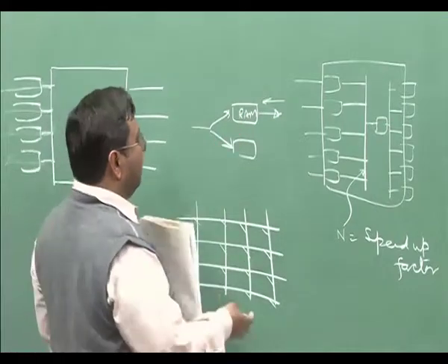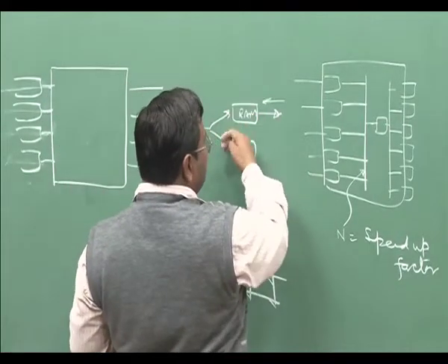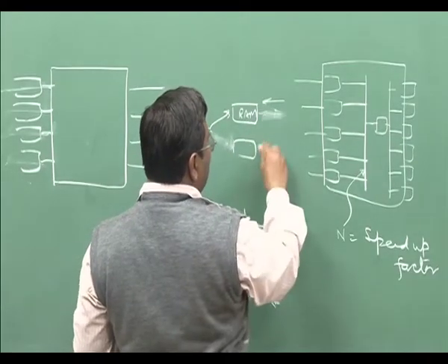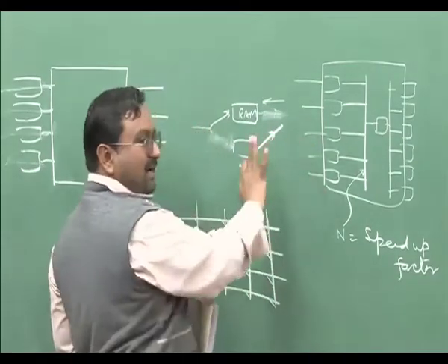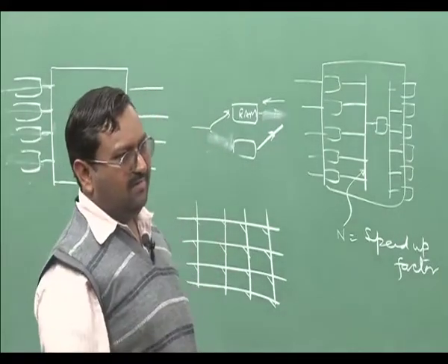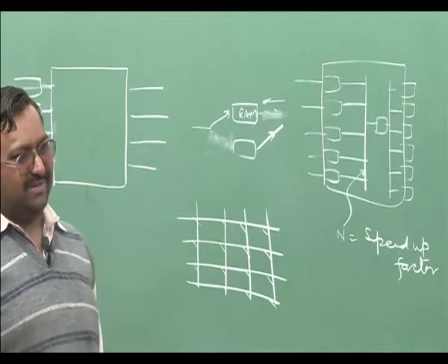And what will happen is, once this has been read out, the next slot you will be writing here, and the readout will be happening from this. All address, everything remains the same. So, just do a very fast flip flop. Actual implementation will be something similar.